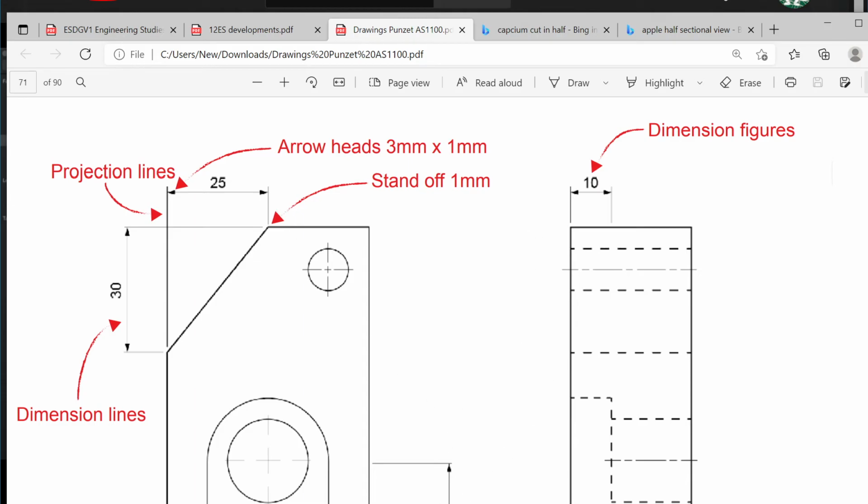There are all different ways that people can help you remember it. Something they say is you should always dimension in the direction that if you were to hold the paper by its staple, let gravity fall and then read upwards. That's fine, that works, but I just like the idea that if you write the number 4, the 4 should point to the staple.